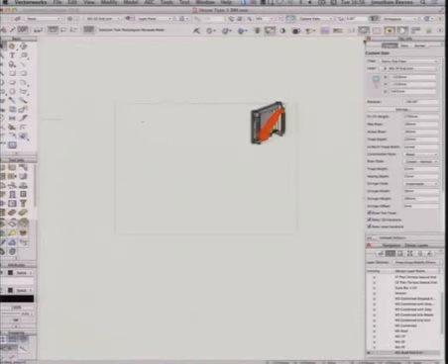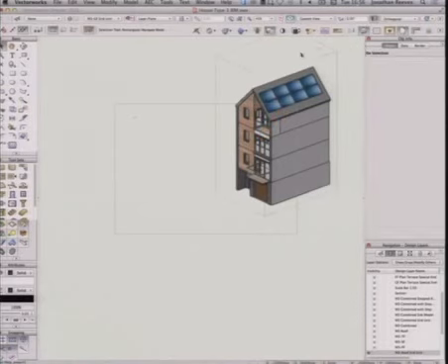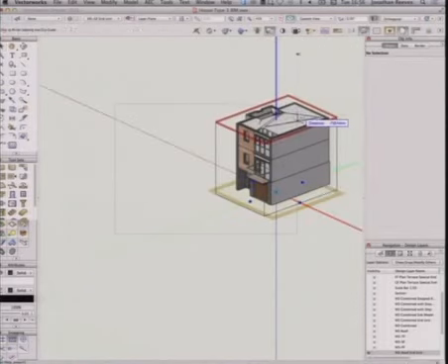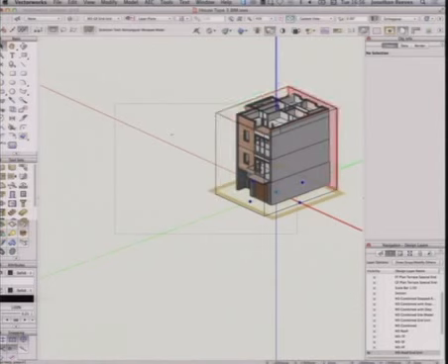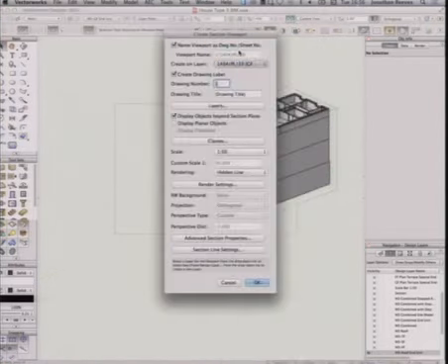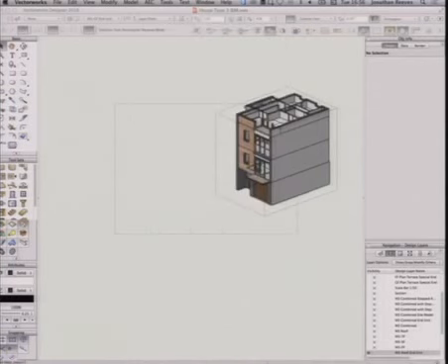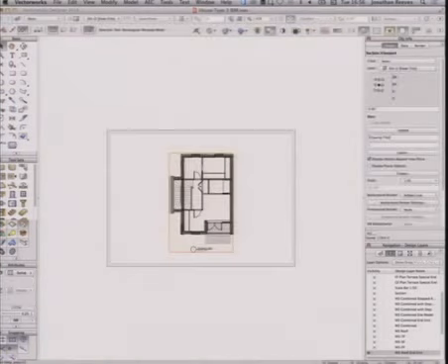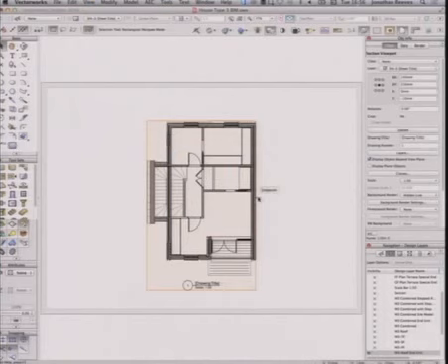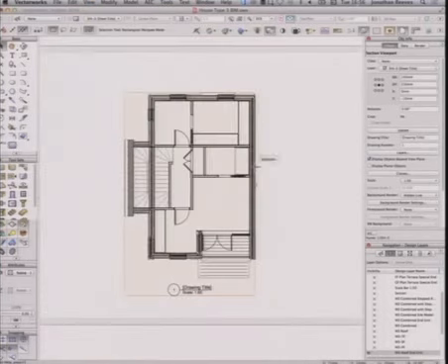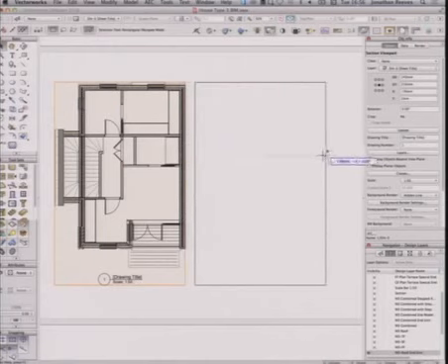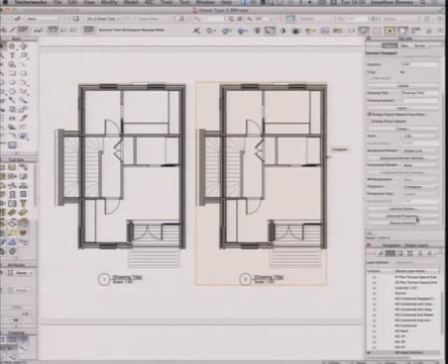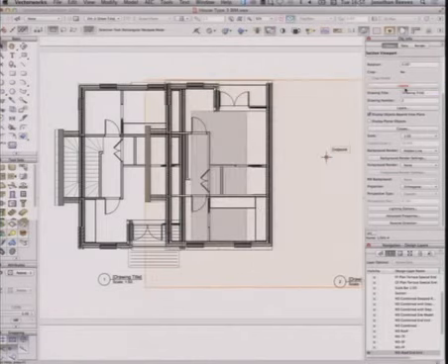Now the ability to plan section, i.e. generate a top-down view at any height, is an absolute gift, really. So create section viewport, put it onto a sheet layer, click OK a few times, and there's a section. And the beauty is I can look up or down. So if I wanted to do a reflected ceiling drawing, I just copy off that viewport, reverse the direction, click update, and now I'm looking up.